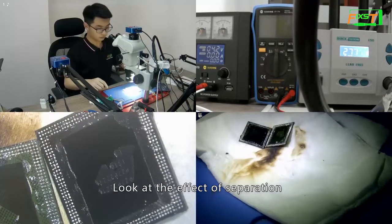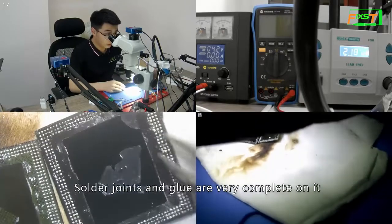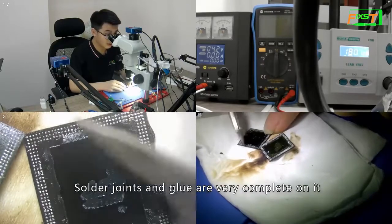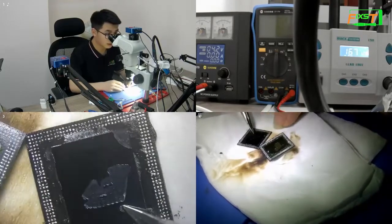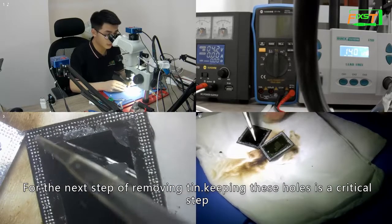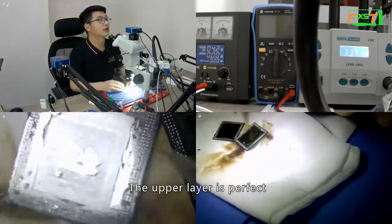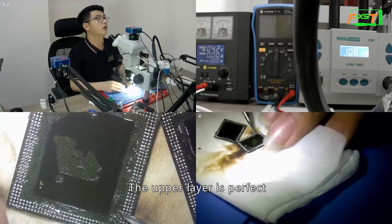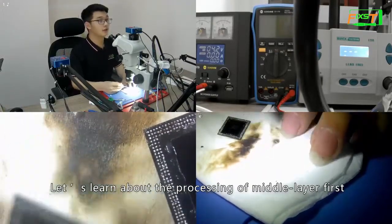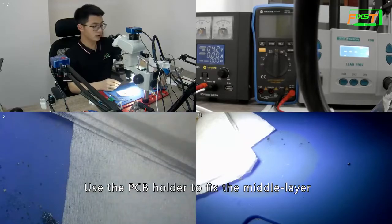Look at the effect of separation. Solder joints and glue are very complete on it. For the next step of removing tin, keep this hole, it is the critical step. The upper layer is perfect. Let's learn about the processing of the middle layer first. Use the PCB holder to fix the middle layer.